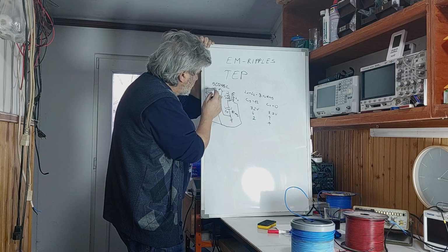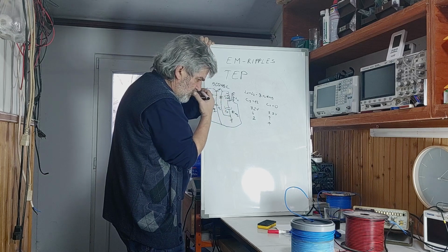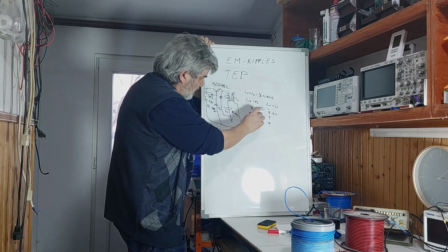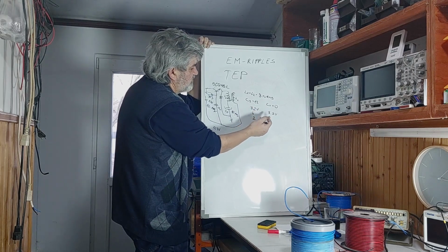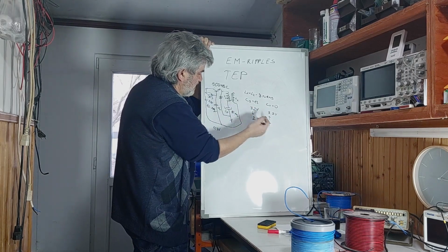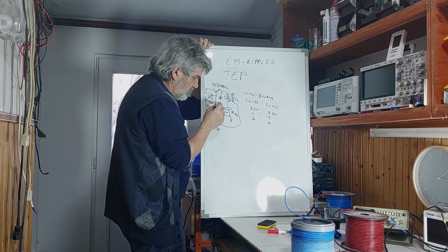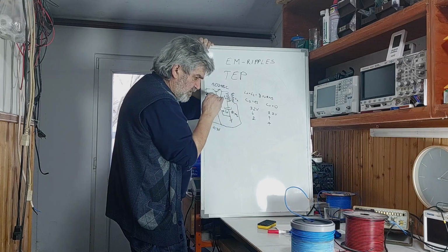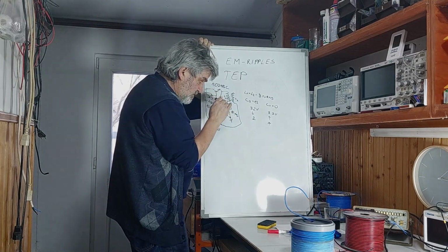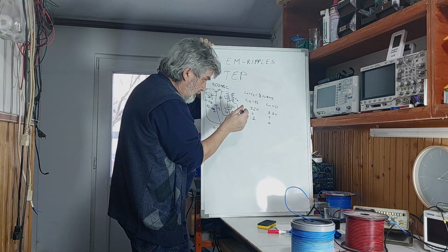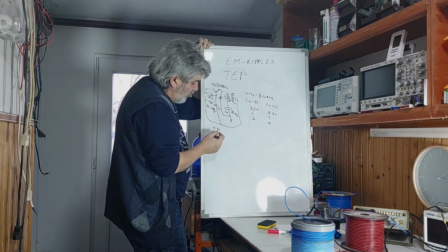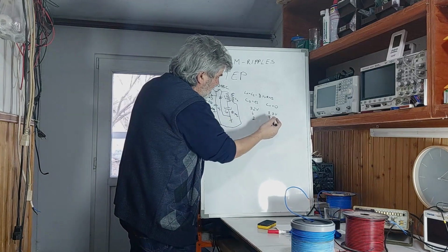Another reason could be that this transistor has a minimum voltage. I think that is about 0.3 volts. So when we got 0.3 volts between source and target, the transistor is not working, and then the source capacitor starts to recover, and this one gets over 0.3, and there's energy again.